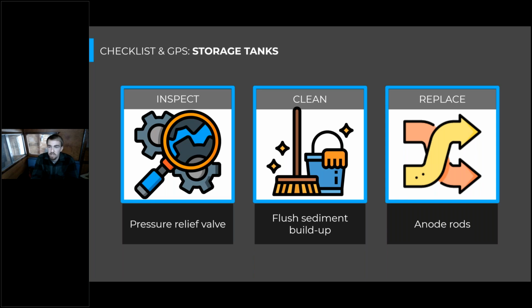So there's going to be different maintenance requirements to these components that are more finely attuned to these different conditions. Like the condenser in a VRF heater is going to be an indoor component that doesn't see the same conditions as say the condenser in a heat pump water heater that is heating water typically outdoors. So the heat exchanger is totally different.